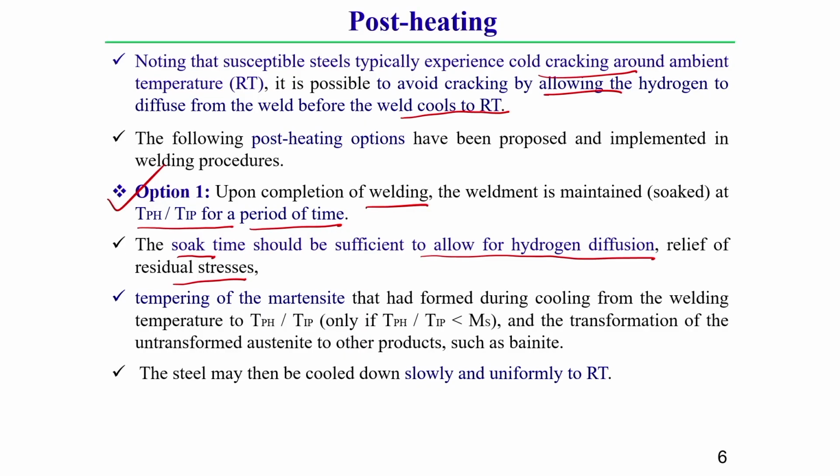So, in option 1 we temper the martensitic structure formed during cooling from welding temperature to preheat temperature.